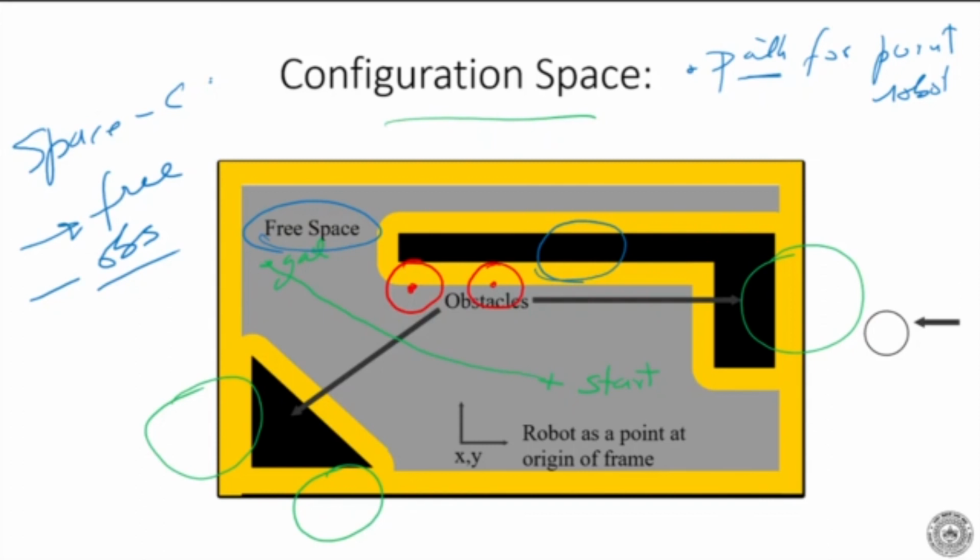And that's not very difficult because geometrically you are moving a point. So if you know the coordinates of this point, or you know the vertices, you know the coordinates here, right? So you can just check that the point should not go inside anywhere there. That is the meaning of the robot going inside an obstacle. So the paths are basically planned in Cartesian space, and this is how we come to the Cartesian space.